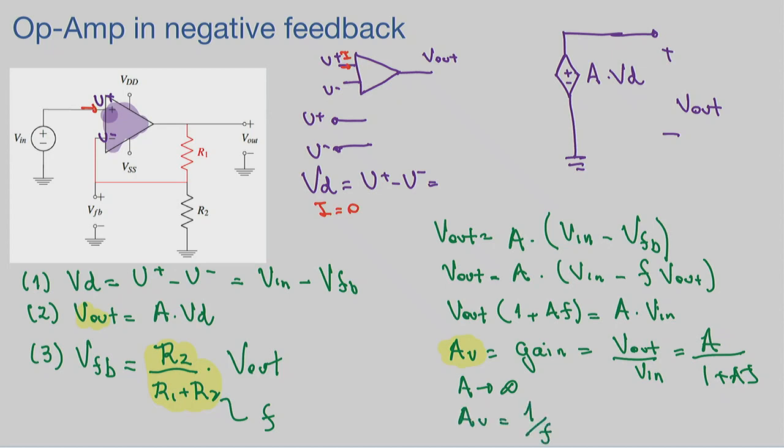And in our case, our F is the voltage divider term. Now you can see that if you do 1 over F, when F is defined as R2 over R2 plus R1, it is going to give you 1 plus R1 over R2. So when you pick the right combination of resistors, you want a ratio such that this number will be 2, in order for you to get a gain of 3, an amplification of 3 in your system. Okay, so